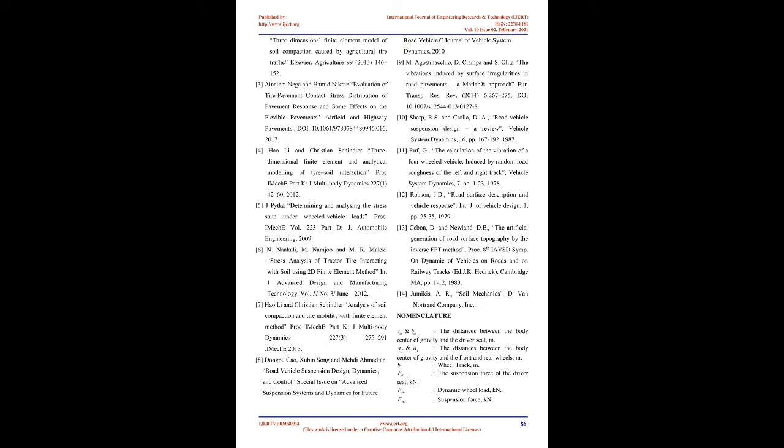The theoretical results of elastic theory in the most basic case of loading acts on a solid, homogeneous, elastic, semi-infinite, and weightless medium are used to support this theory. The load is vertical, pointing on the horizontal boundary surface, in this case, the road surface. Radial distribution of stresses in the semi-infinite medium is assumed under one concentrated load. The assumptions of Boussinesq are that the earth is weightless, the soil is stress-free before the effect of the point load, stress continuity, and stress symmetrical axis.